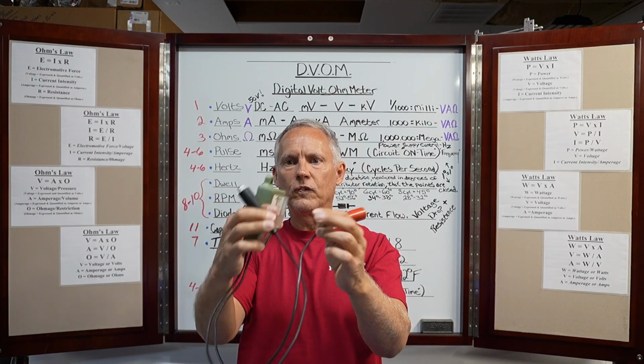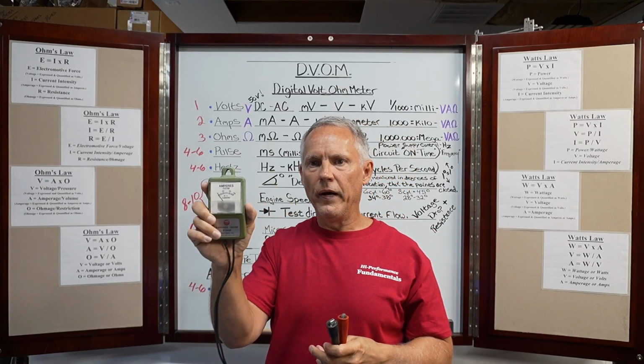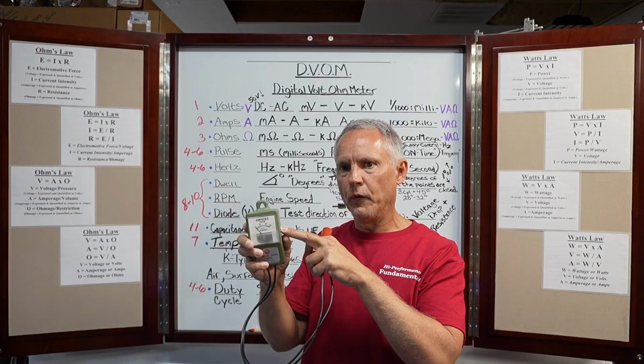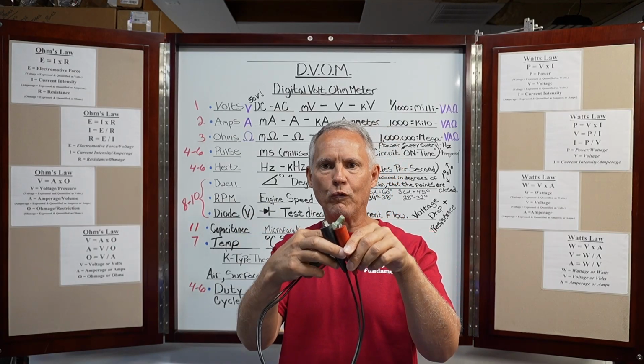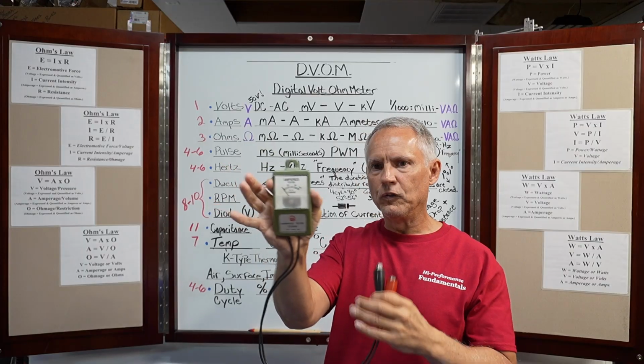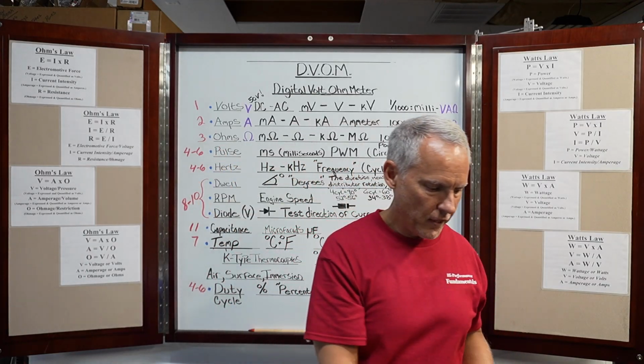So now you literally have opened the circuit, and all the current has to flow through the ammeter. That's an inline ammeter. There's no doubting what you're going to see because all the current is flowing through here. You basically broke the circuit open and stuck this in series, and the ammeter is going to read what's flowing through it. So that's an inline ammeter.